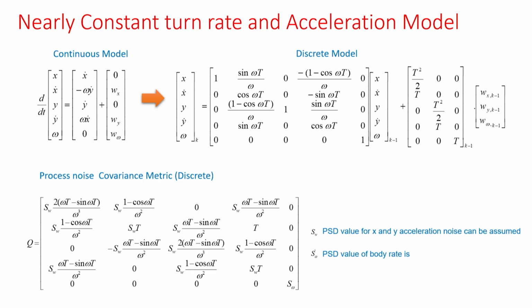Okay. So, how these equations have come up, let me derive it here. Suppose you are maneuvering, okay, the target is maneuvering. By the way, the CV model is only the non-maneuvering model. CA and what I am now doing, the coordinated turn model, these are all maneuvering models. You have to know both models for your tracking application. So, this is your, say, tangential velocity. The normal component is anyway, there is no normal component. So, it is your tangential velocity. So, here is your heading.